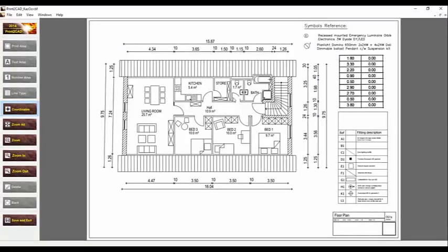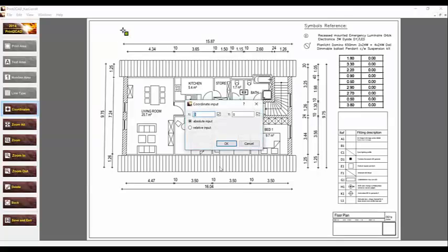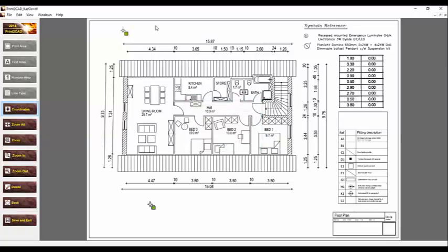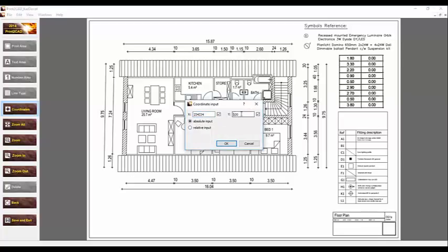Now we go here to the subject, and here you can put 10, 20, 50 calibration points, and a calibration point can be every time on the end of a line, because we snap to this end of a line. Don't put the calibration points like me here, so this can be a calibration point, for example here, with coordinate 100, 100, because with these calibration points you are not able to increase the accuracy, because what do I snap here? I snap on a pixel on a screen. So every time you define calibration points, define the end of lines. For example, you can snap this corner, okay? And if you know the coordinates of this corner, you can put this coordinate here.